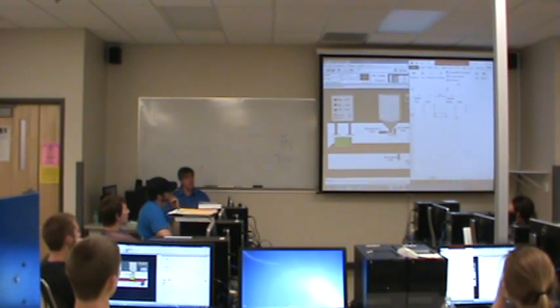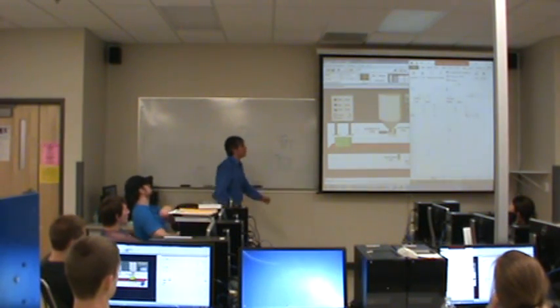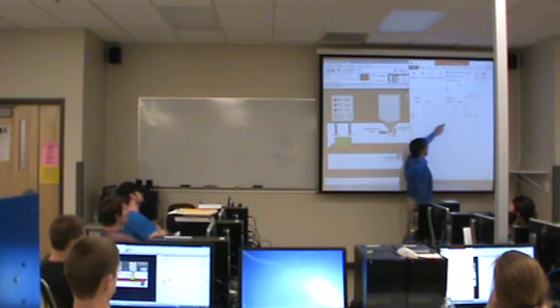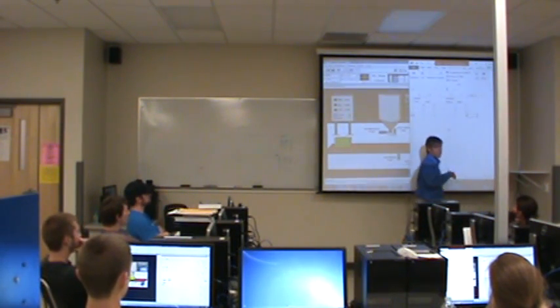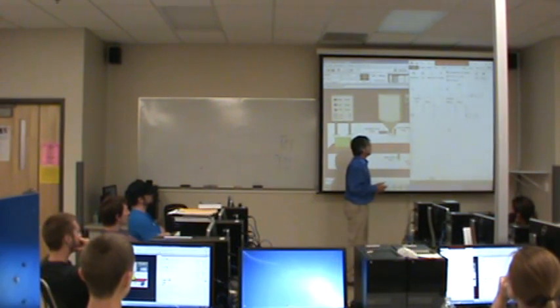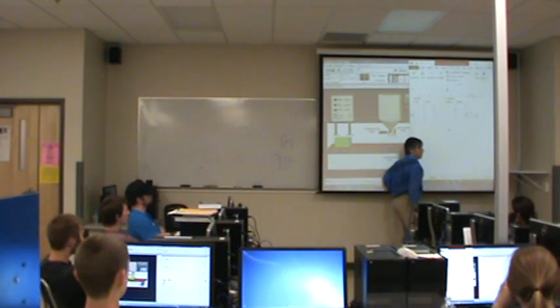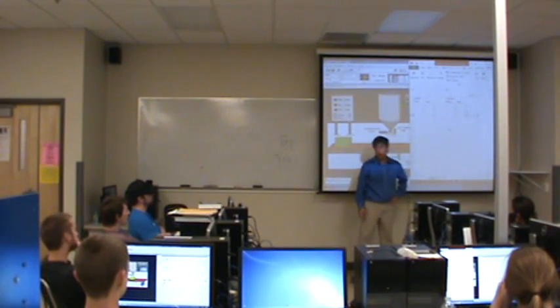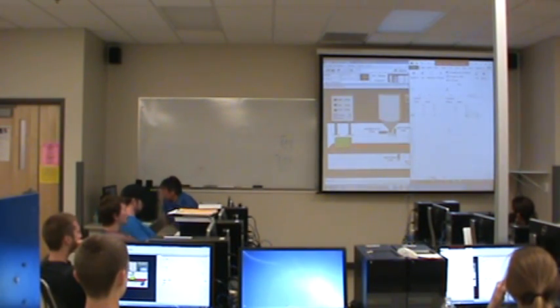Now, let me warn you, this is an unnecessary step. We don't have to have this in our sequence because the outputs don't change. You see that? Anytime you see inputs change, but outputs not change as a result, it's unnecessary to have that step. We can leave it in, it doesn't matter, it won't hurt anything. Really what we're looking for is no box and no level. Right? That's what we really want to find. But I'll go ahead and program it this way so that we will have 4 steps in our program.